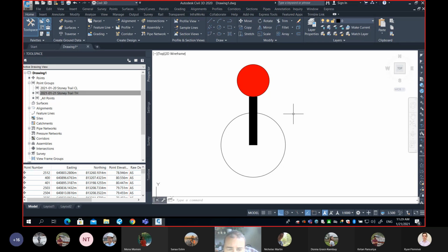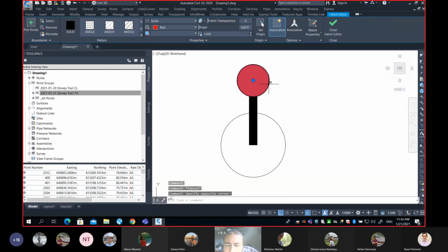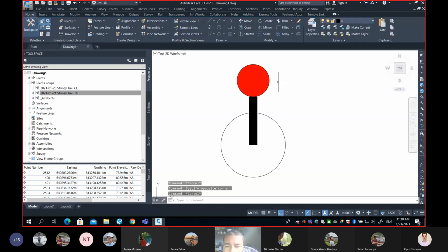And you guys know what a block means in AutoCAD. Block means grouping. We're grouping so many CAD elements into one entity. Grouping many CAD elements into one CAD entity, that's called a block. Look at this, please. Right now, this is a circle, this is a polyline, this is another circle, and this is a hatch, which means how many? I have a total of 4 AutoCAD elements.